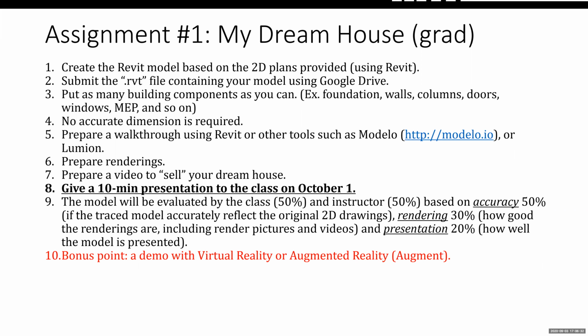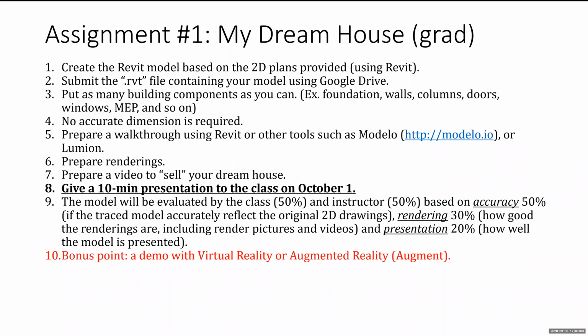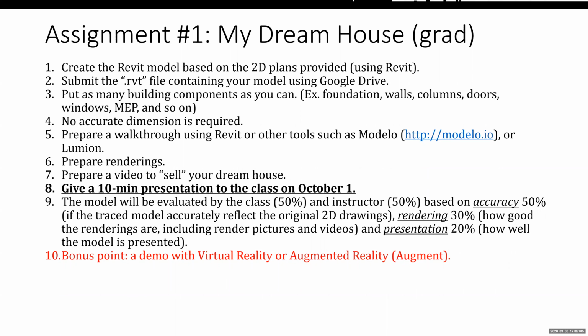Liability. When you downgrade the dimension to 2D, you can have a lot of potential errors and data. Make sense? When you are sending a 3D model, I'm not talking about just a 3D model. I'm also talking about all the data that comes with the Revit model. For example, the insulation rate of a door or a window, the material, the PSI of your concrete, the supplier's telephone number. Everything can be stored in the Revit model. If you're sending that, you are running a lot of potential liability issues. Make sense, guys? So why AutoCAD? Because the contract only says AutoCAD. I will just fulfill the contract requirement. I don't want to share my BIM model.